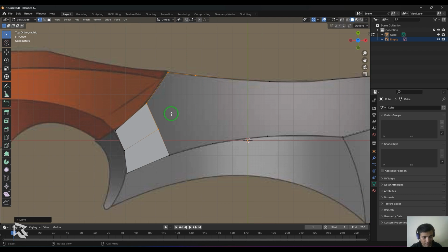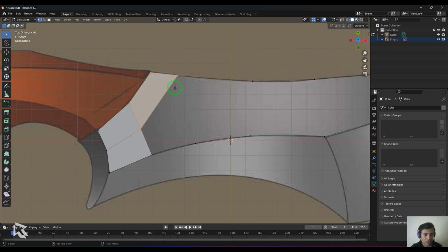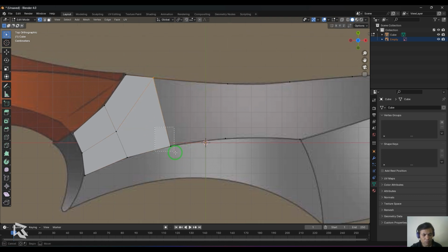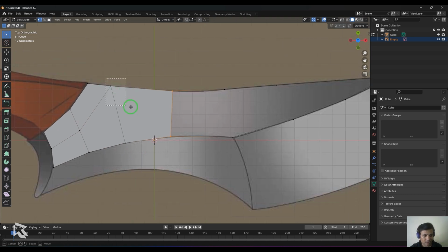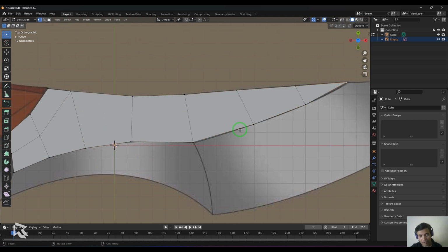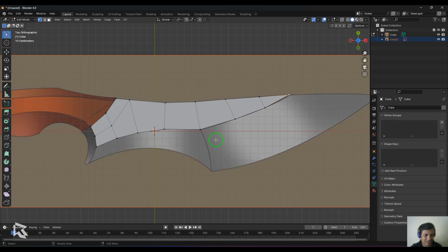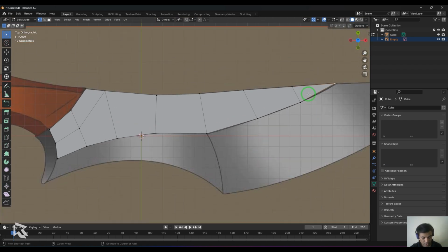So I'm going to press F to fill those points there. You keep selecting those points and then start filling them. And the last 2 points, once we select them and press F, that fills to the next set of points. So you need not select the 4 points like that. Instead, just select these 2 points on the side where you have additional points. It will start filling those points, and then it fills the overall geometry, and that's how easy it is to create this particular patch.